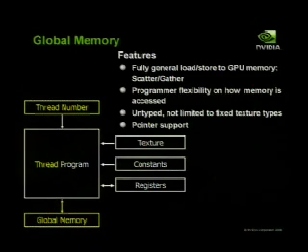One big complaint, obviously, was the inability to scatter. The access to memory was super constrained. So we opened that up. We have a fully general load store to the GPU memory. The memory that's on the board, there are load instructions and store instructions. There's no restrictions on how you can access it. It's really just like a CPU here. This was an obvious one.